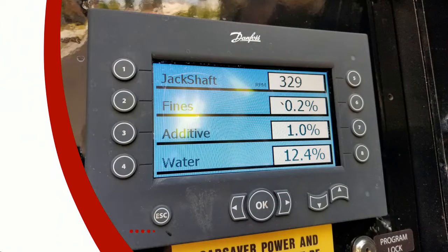The computer system, we have real-time percentages. Because these machines are mobile batch plants, they are mixing the chemistry on site. So they're making this material. We have to measure the material within 0.25% as we're mixing some of these ingredients together. So the computer, and everything that I'm showing you is all standard equipment. It's not an option. These are all just standard pieces.